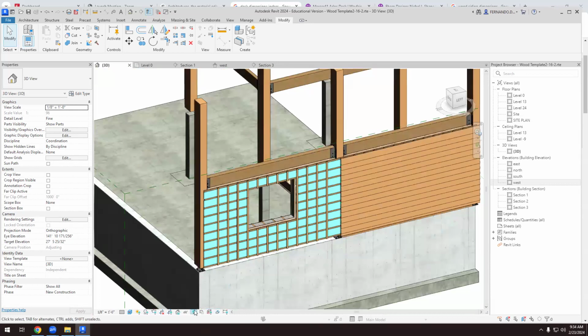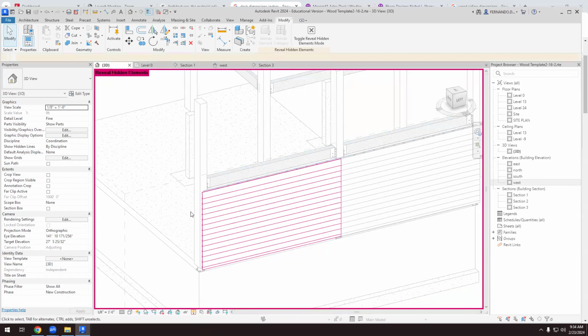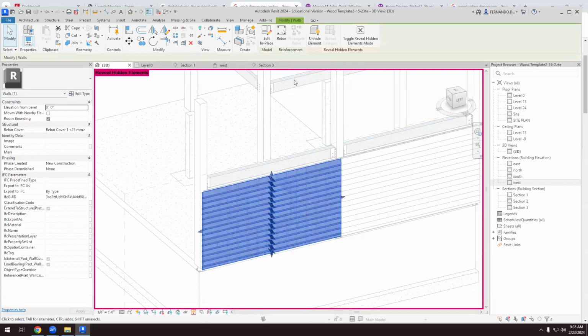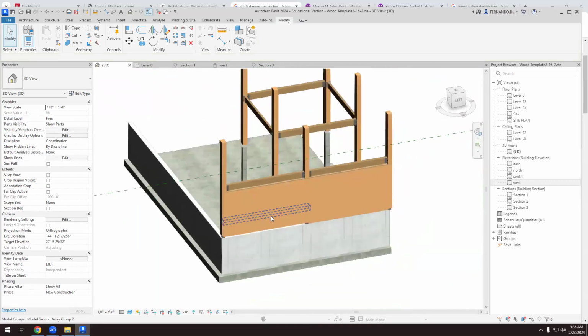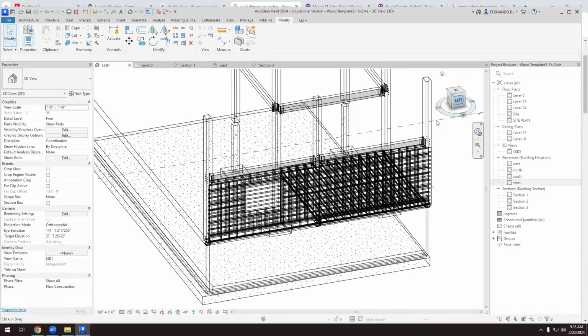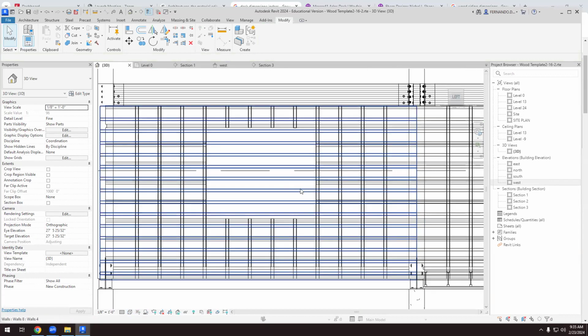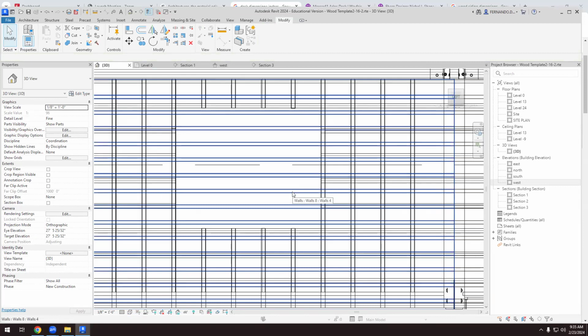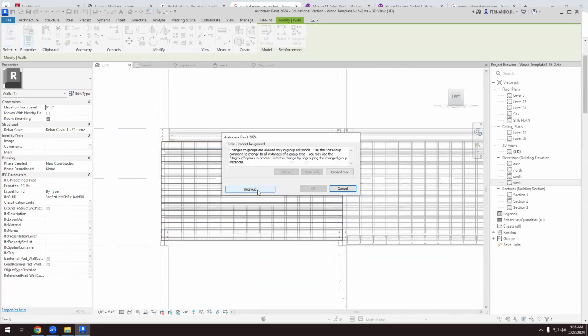I told you that now I can reveal the hidden elements. So we still have this siding. So let's unhide it. And yep, you thought that we were done with it. We are not. So we have to go to the wireframe. And now we have to open the void in the siding. So if the siding is a component model in place, I have to edit in place.